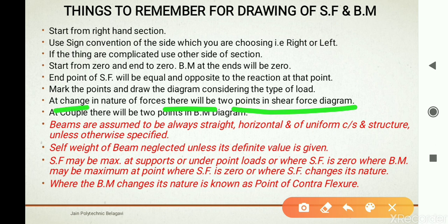Change in nature of forces means sometimes you come across combined forces, point load as well as UDL. So keep in mind that there will be 2 points in the shear force diagram at that particular section.